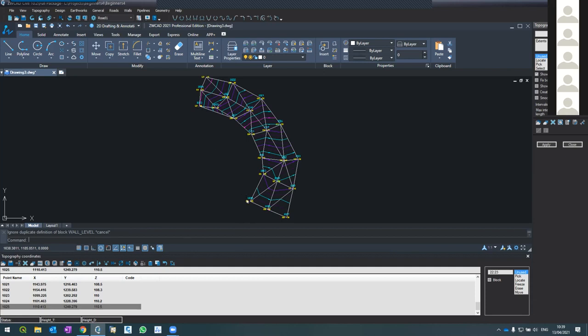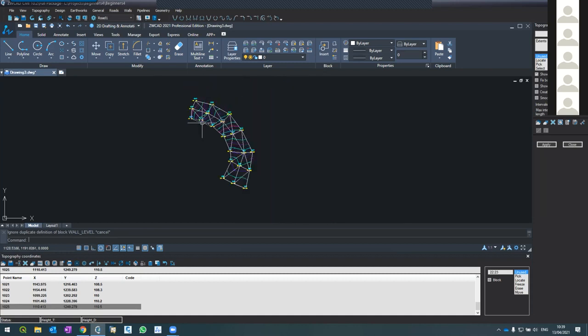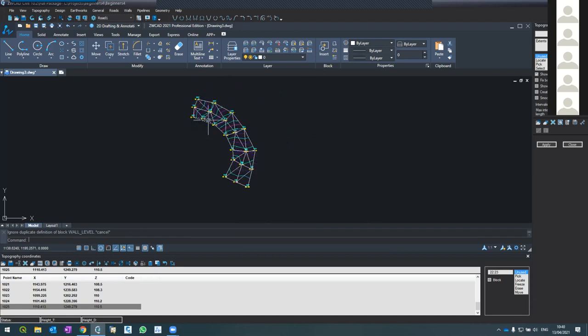So this triangle, or this triangle, or this triangle, all the triangles that have an edge with more than 65 meters were removed. Now we see that there is a small triangle here. Either we leave it as it is, or we fine tune it. It's not so important. In fact, I'm not sure what is correct. We can leave it as it is. But the principle is maximum interpolation length. Each triangle which is longer than a specific length, this is what we do.